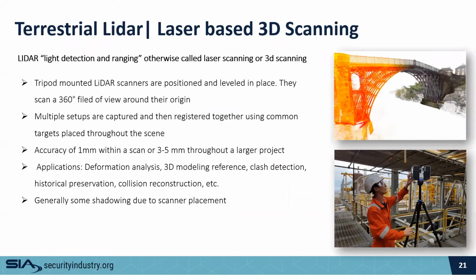So terrestrial LiDAR is commonly a technology we use for modeling, for monitoring and high precision documentation, millimeter accuracy. So typically the instruments are a little more expensive based on the sensor you're acquiring. You'll get a better quality of result, but usually using a tripod, usually needing to have that to scale, introducing targets.